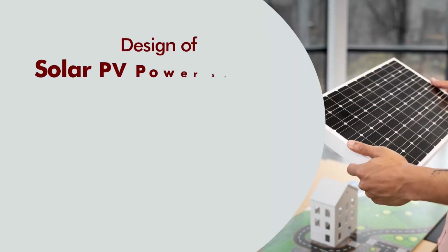For a typical LED information system of size around 1 by 2 meters and consuming about 300 watts of energy, a solar photovoltaic module of about 2 kilowatt peak capacity is required to enable it to operate all throughout the night. For a 300 watt system requiring 15 hours of operation, the approximate cost can be about rupees 7 lakhs. Now again we will discuss the solar PV power system.